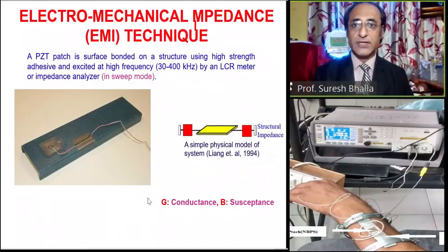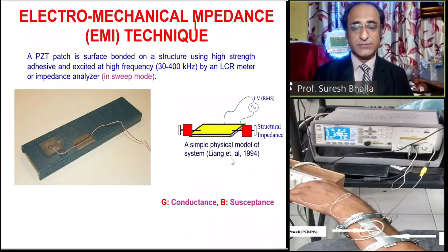The electromechanical impedance technique is a relatively new technique, and it employs piezo sensors both as sensors as well as actuators. Here we bond the piezo patch on the structure and excite it into vibrations by applying an alternating voltage source. The piezo starts vibrating, but in this process it interacts with the structure dynamically, and the structure also modulates the vibrations of the piezo patch. Not only that, it also influences the electrical circuit comprising the piezo patch and the device.